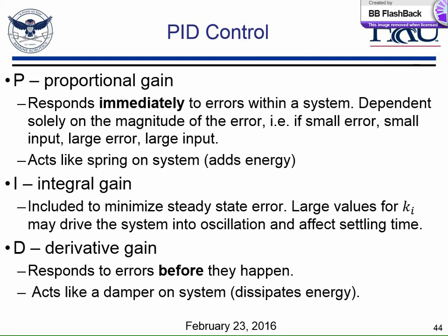With a P controller, there are lots of approaches that you're able to use to tune. How many of you know what a root locus plot is and how to tune a root locus? I remember vaguely. Vaguely, yeah. When you have two poles, you have to point towards it, and if it's in between, it's not good. Somewhat. So yeah, it's a lot easier if you just use rlocus in MATLAB. At one point in my life, I knew how to do it by hand. But a root locus plot is basically a way for you to tune a single gain in your system.